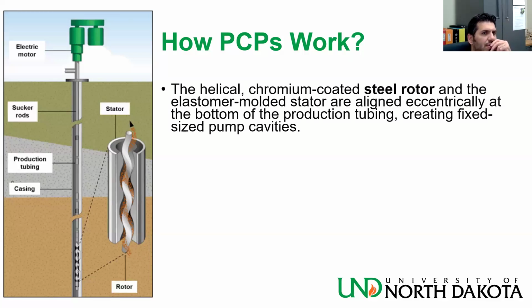The helical chromium-coated steel rotor and the elastomer molded stator are aligned eccentrically at the bottom of the production tubing, creating fixed size pump cavities. So as this is rotating,